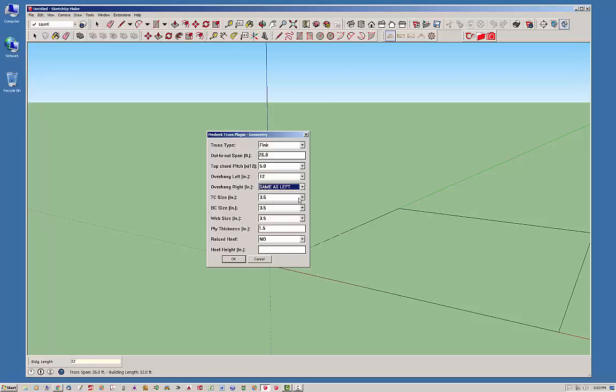So typically, with a basic truss this size, a 2x4 is your regular size member that you're going to see here. So 3.5 is, and that's why it defaults to 3.5. Usually it's going to stay at 3.5, but you can alter and modify these to any size of lumber that you choose. And you'll notice I have some preset lumber sizes in here. With the metric version of the software, this actually opens up and you can use any size you like.